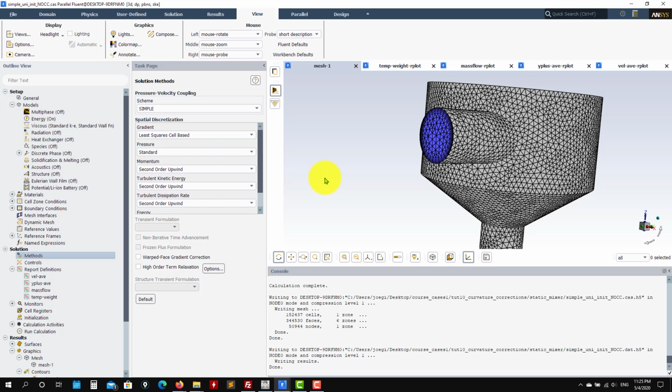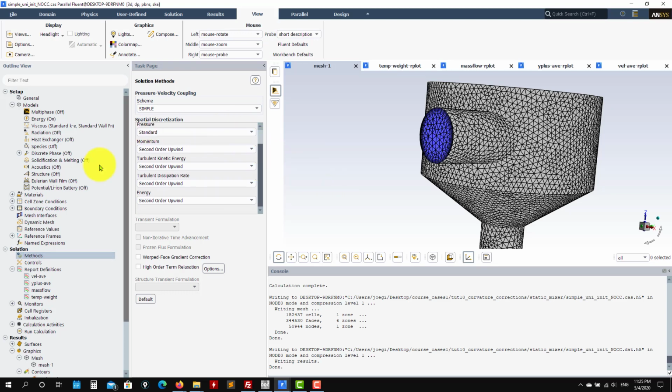So this is a nice case. You can play with this configuration we saw already, and I will show you different behaviors so you can get an idea. You can run the first case using SIMPLE, and let's go through all this setup, everything, let's use second order accurate. By default Fluent will propose that the turbulence quantity is first order, which is okay, but let's go everything second order accurate.